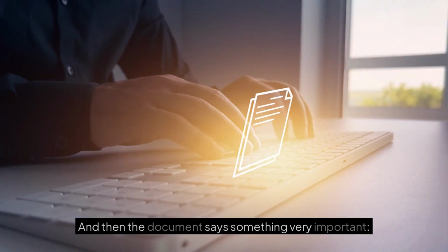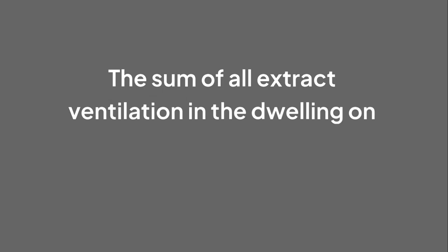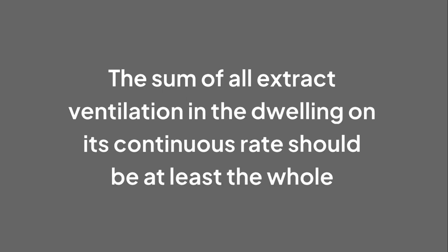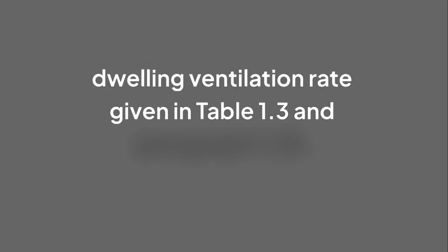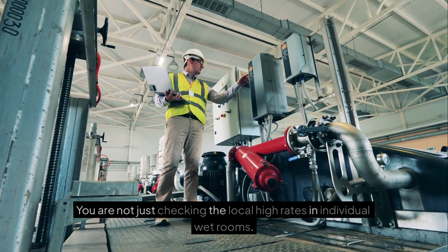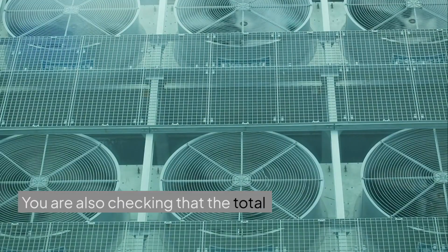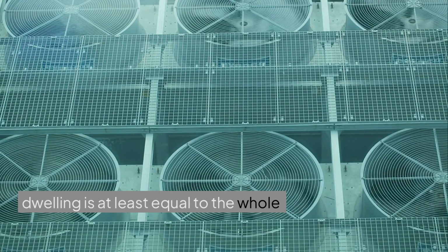And then the document says something very important. The sum of all extract ventilation in the dwelling on its continuous rate should be at least the whole dwelling ventilation rate given in Table 1.3 and paragraph 1.20. That is one of the biggest junior engineer takeaways from this topic. You are not just checking the local high rates in individual wet rooms. You are also checking that the total continuous background extract across the dwelling is at least equal to the whole dwelling ventilation requirement.